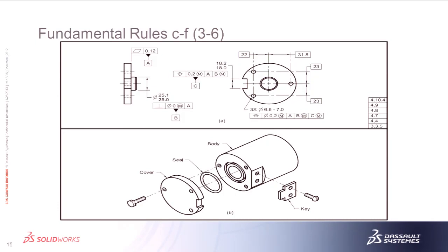So keep in mind the function of the part when you're dimensioning, and to a point, also the quality and manufacturing guys would very much appreciate it if you keep in mind their job also. You can greatly reduce inspection requirements and manufacturing cost by taking that into account when you're doing your design and dimensioning on your drawings. Especially your datums, how you select your primary, secondary, and tertiary.